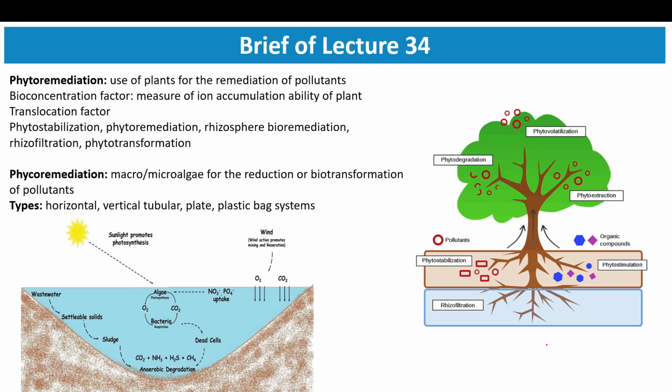Now moving forward, another type of advanced treatment technology is phytoremediation and phycoremediation. So here it is a very environment friendly method. In phytoremediation, phyto means related to plants or trees. So here you utilize plants and trees for the remediation or removal of pollutants from soil or from groundwater or any source.